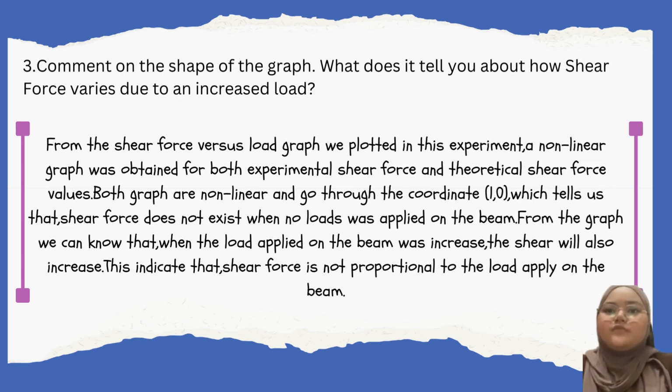From the shear force versus load graph we plot in this experiment, a non-linear graph was obtained for both experimental shear force and theoretical shear force values. Both graphs are non-linear and go through the coordinate 1, 0, which tells us that shear force does not exist when no load was applied on the beam. From the graph, we can know that when the load applied on the beam was increased, the shear will also increase. This indicates that shear force is not proportional to the load applied on the beam.